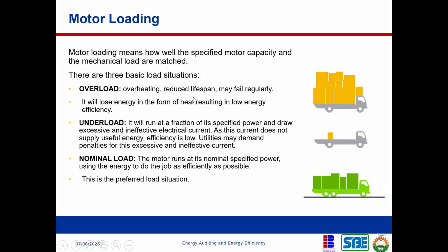It will lose energy in the form of heat, resulting in low energy efficiency. Then if you underload the motor, it will run at a fraction of its specified power and draw excessive and inefficient electrical current. As the current does not supply useful energy, efficiency is low.